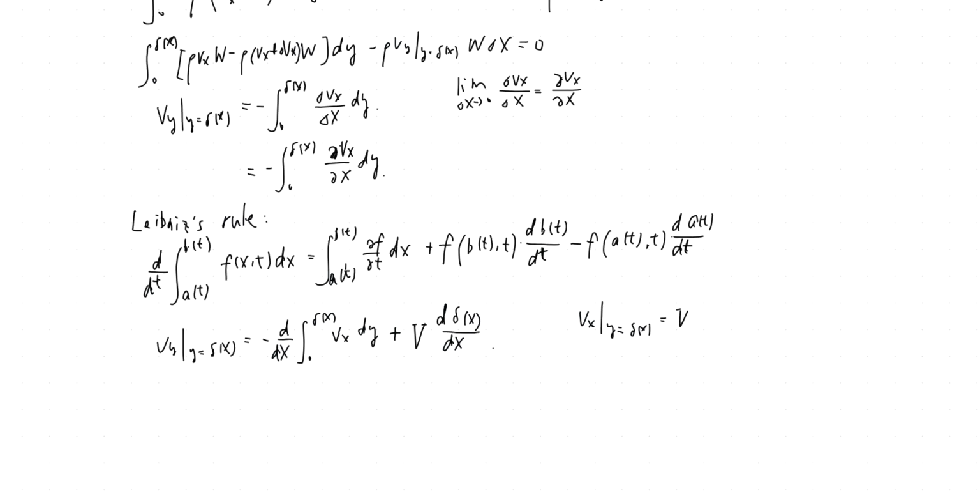This is the definition of the boundary layer. You may say, well, it should be 99% of V. Oh, that's true. Here we are using an approximation. So the 99% is a numerical criterion people use because we needed to define a criterion anyway.